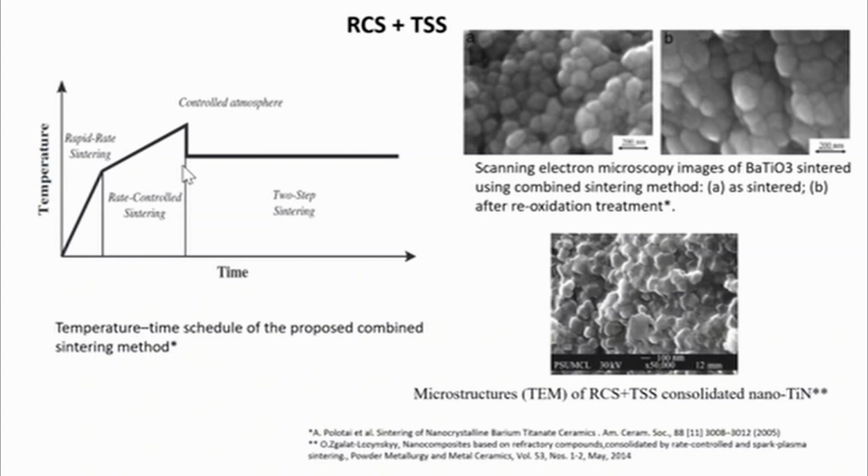Composite two-step sintering, which was proposed by Chen and Wang, exploits the competition between grain boundary controlled densification and grain boundary controlled grain growth to achieve densification without grain growth during the final stage of sintering. This problem is identical to the one of the final stage of rate control sintering. The success of two-step sintering is determined by the pore morphology of the material prior to low-temperature second-stage sintering.